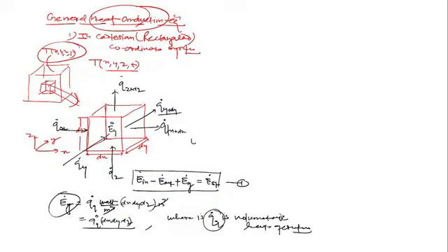Now what is energy stored here? E dot stored. Energy stored is simply accumulation. Energy can be stored only in the form of internal energy, yes or no? This is d of u upon dt. It's the rate of change of internal energy that is stored in the system.